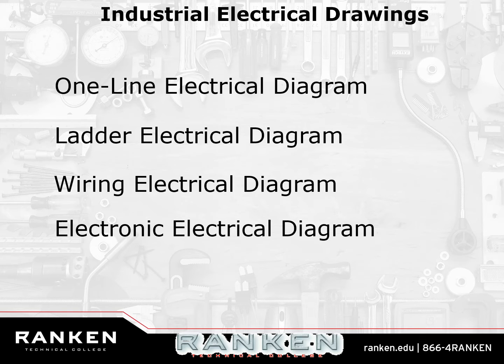Anybody know? PLCs. Not only PLCs, just troubleshooting in general, right? Ladder diagrams are used for troubleshooting. They don't give us an idea of how the thing is physically wired, or even in the order that it's wired, right? It just gives us an idea of what it takes to turn this on. That's one reason why we use them in PLCs, is because it's about logic.